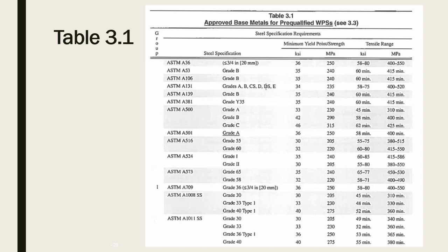We were doing some work in China and in Vietnam and down that way, but there were a lot of Chinese steel fabricators, and they'd try and send in a pre-qualified WPS with some Chinese steel, and it's like, no, it could hypothetically be the same, but unless you've got paperwork that says it's ASTM A36 or A572 or A573, you can't use it. Go do a qualification. So just something to think about.